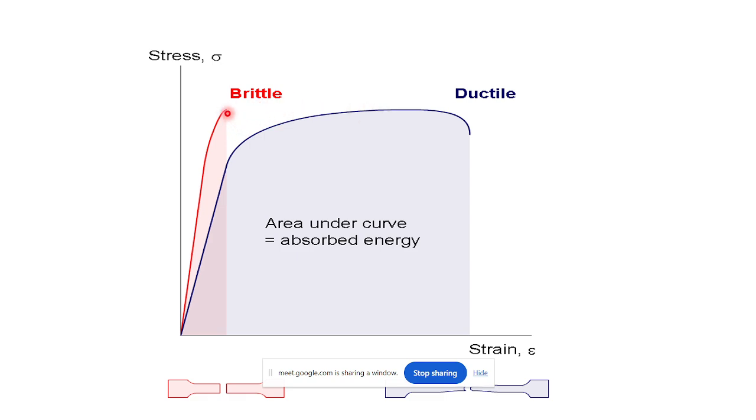This is a simple stress strain curve for brittle type of material or ductile type of material. For brittle one, we know the modulus is very high, but the elongation at break is very low. So after certain strain, it will be broken apart. And also from the nature of the cracked surface, you can predict what is the nature of failure.